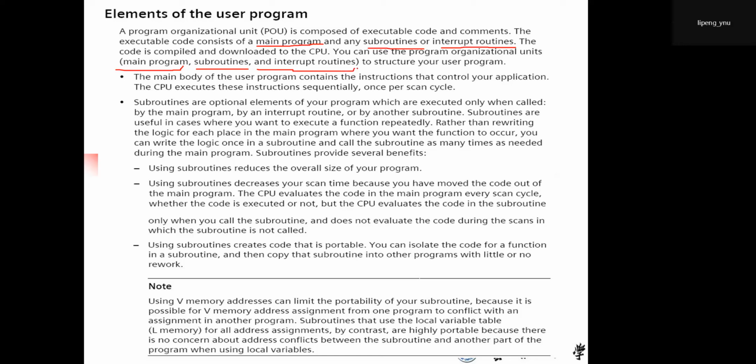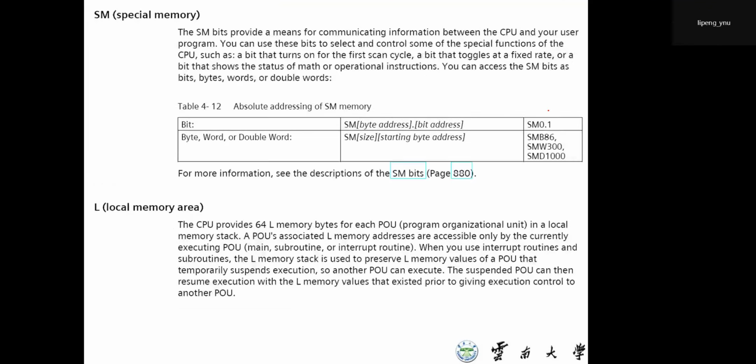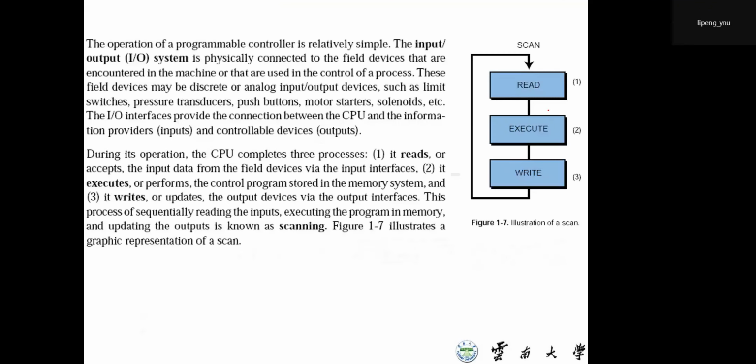The CPU executes these instructions sequentially once per scan cycle. What is a scan cycle? I just introduced it to you. It includes reading, executing, and writing.